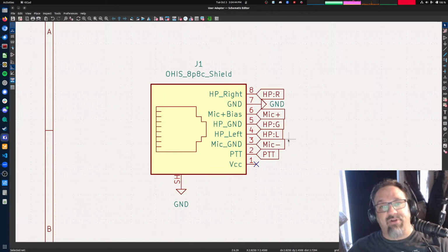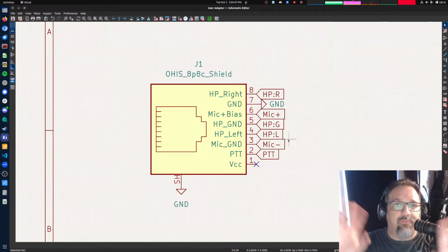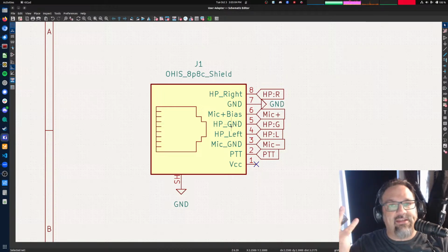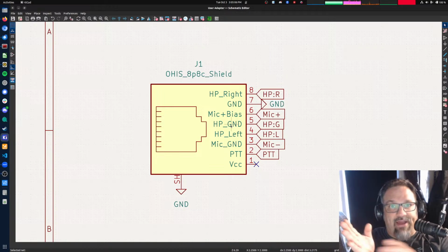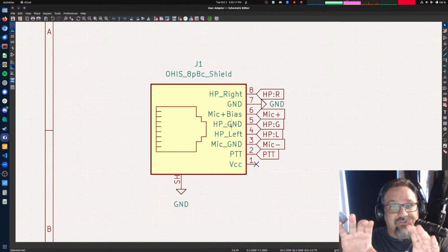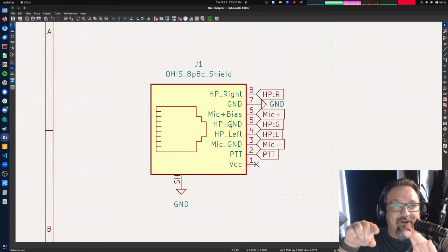Now, good cable is going to have pretty darn close to 0 ohms, so we can hand wave it and get away with a lot of things. But if you've got enough wires to keep them separate, it's best that you do. And the reason you want to keep power ground separate is, you think it's going to be like a DC current, and if you're just doing LEDs and whatnot, it will be. But let's say you're powering a microcontroller on the other side. That microcontroller has an internal clock, and that clock is going to cause lots of fluctuations in the current draw. That fluctuating current draw is going to cause noise on your ground line, the same as the headphones did.